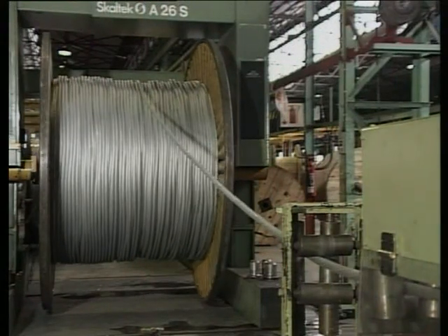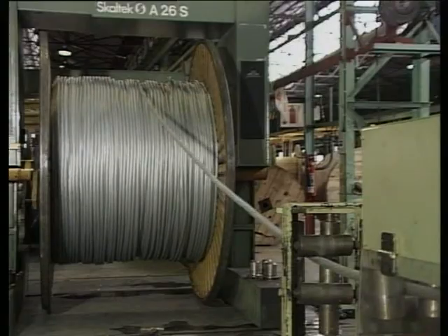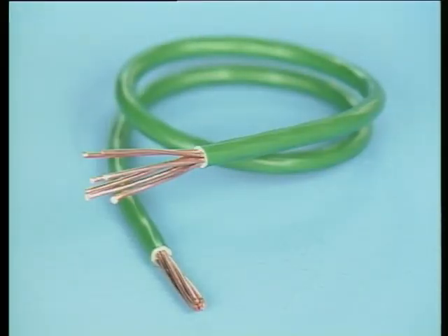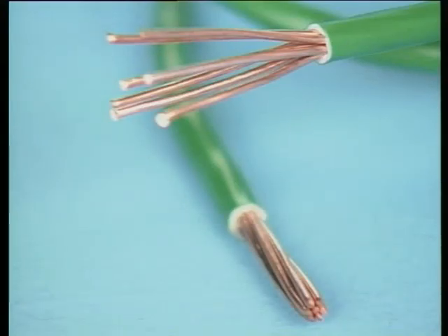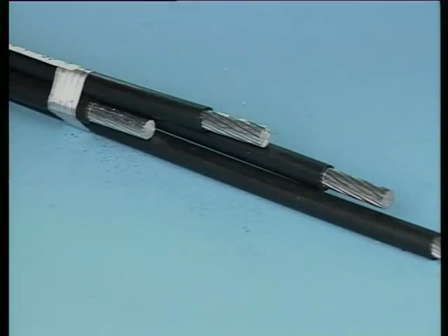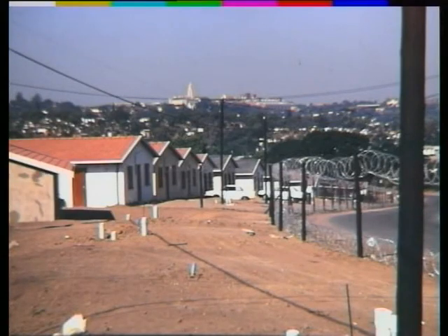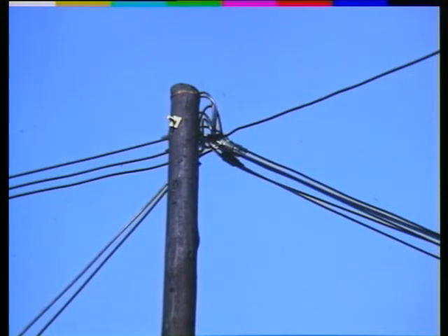Let's look now at typical cable construction principles. All cables are constructed in either single-core design or multi-core design. Single core, the simplest design, consists of a single conductive core surrounded by its insulation material. In some applications, several single-core cables are bundled together to bring in a 2- or 3-phase supply to a development. When brought in on an overhead supply, such a configuration is known as ABC line or aerial bundled conductors.